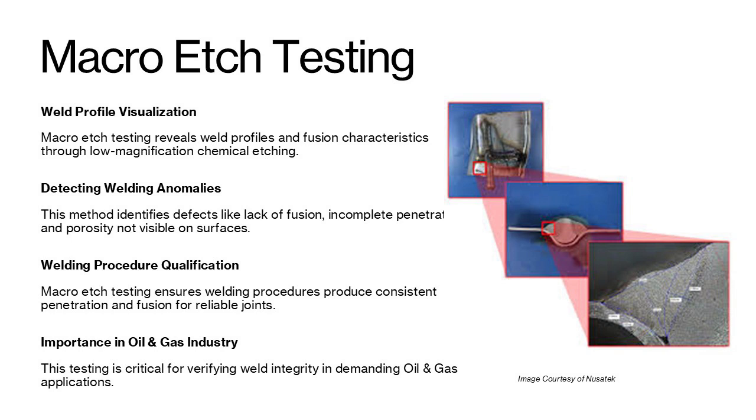This method is particularly beneficial for identifying defects not visible on the surface or those that may not appear on radiographic or ultrasonic examinations. Understanding macro-etch results helps inspectors verify that welding procedures produce consistent and reliable welds suitable for service in demanding oil and gas environments.